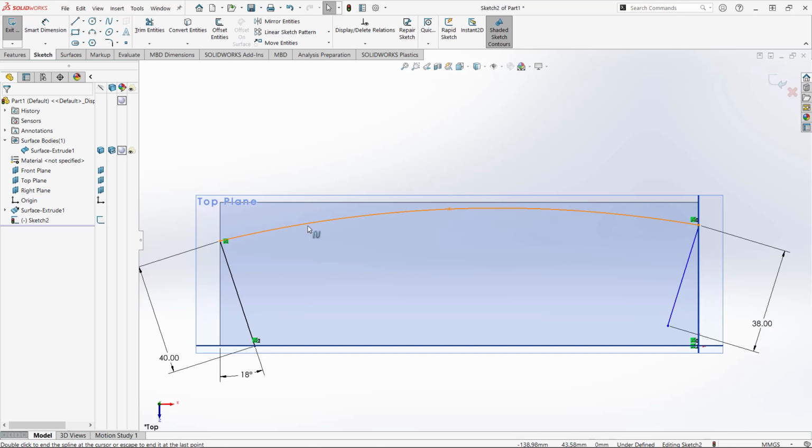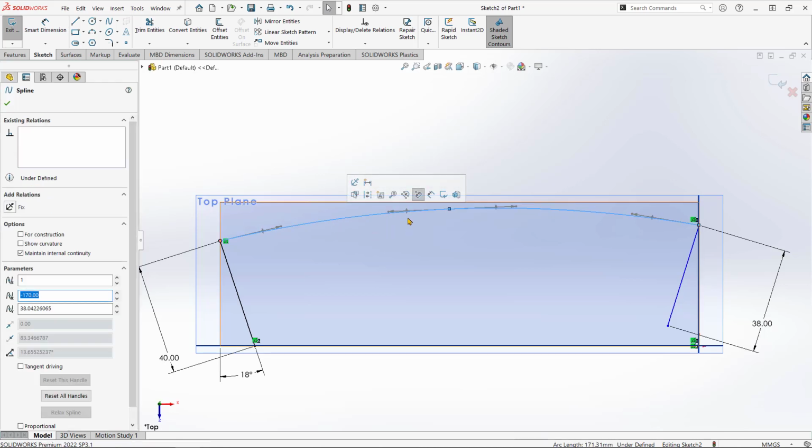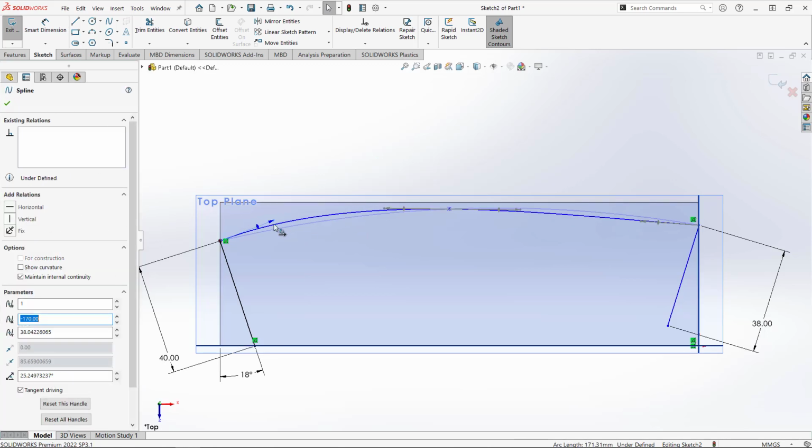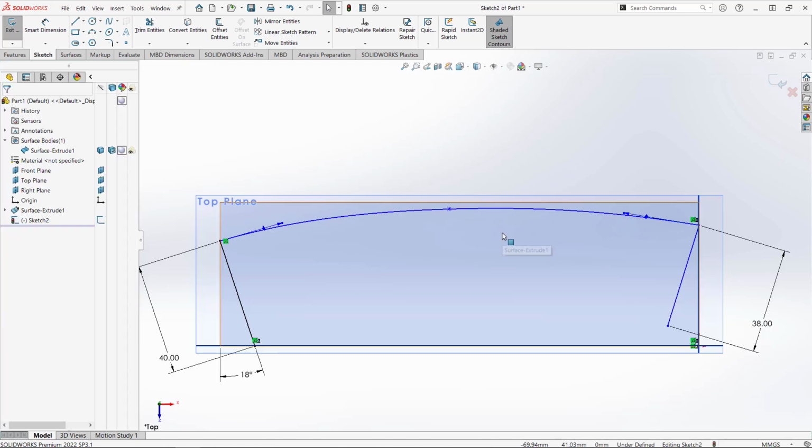And then with these splines, you can edit the influence of any one particular point along the spline, but in order to do that you have to make the spline edit handles visible. And in order to do that, we just have to click on the spline once, the handles become visible, and then in order to make them stay visible when I click off the spline, like I just did there, you just have to drag and edit their position slightly. So as soon as you've edited their position at all, when you next click off the spline, they will remain visible, as we can see here.